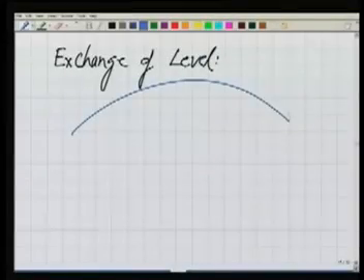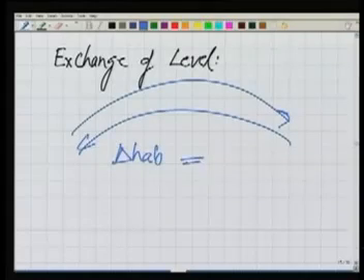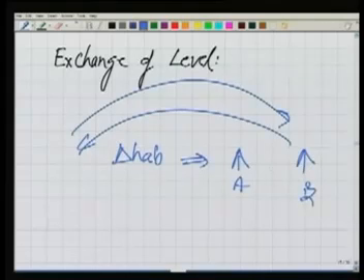Now what if our levels, I was using level 1 at A, level 2 at B. If these two levels have different collimation errors, what should we do? We would like to exchange the levels also, and again repeat it. If this is point A, point B, this is level 1 and level 2, this is how we had done it.